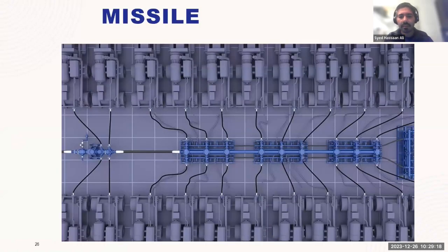Frac missile, this is a term which I've used quite often. So all the pumpers, you have frac pumps on top and bottom, and all of them can be connected through what we call iron, which is nothing except a series of pipes, into the frac missile. This is a large monobore missile. It will take inputs from all the pumps and commingle them into a single flow.